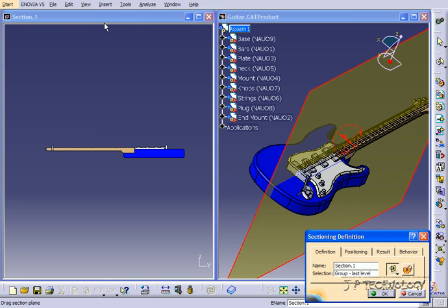Once you've moved all those other windows around and figured out which ones you're going to be working on, and you have them set up like this, you're able to create your section views. This is just to set it up so you can see really what's going on. Now you're able to change the type of section view. Right now we have the section plane. If you do the section slice, you'll see the difference. Now it's just a slice of it. And if we do the box, you'll notice that now we've got our whole part boxed in. Let's put it back to the section plane.